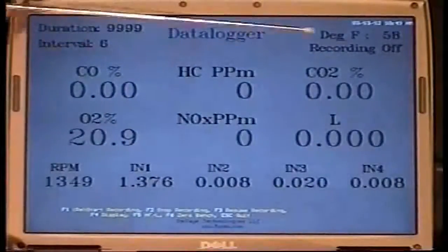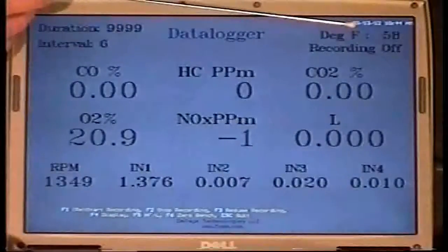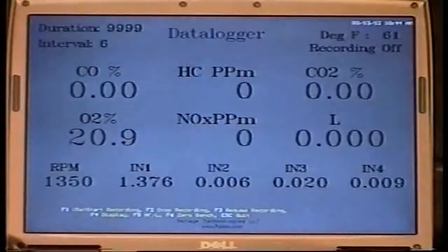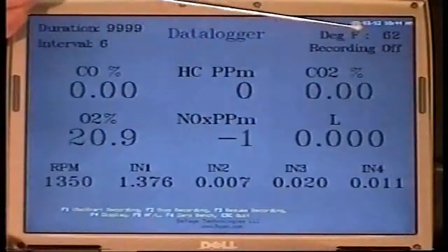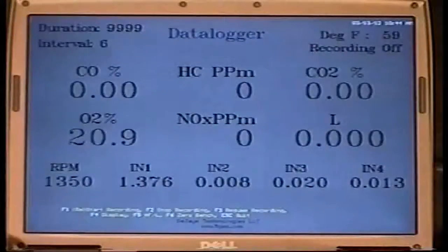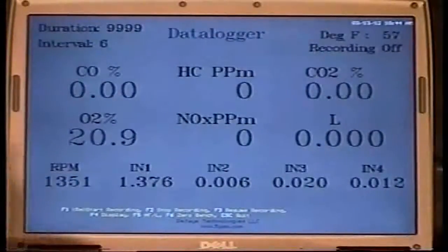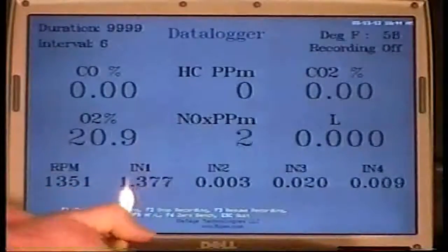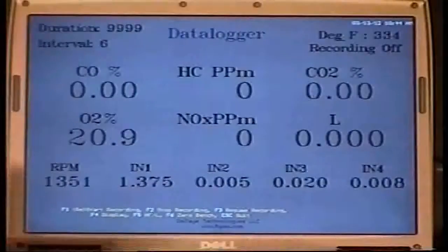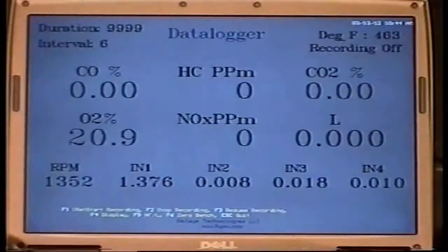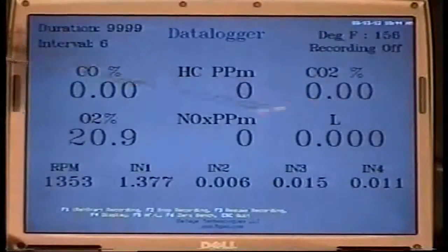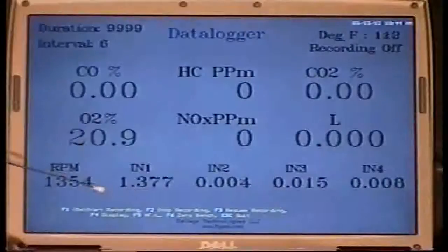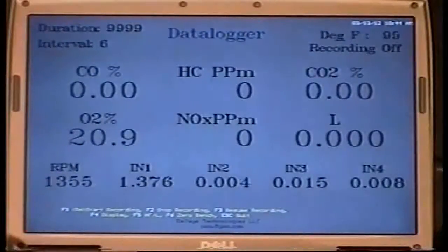We also have a temperature sensor up here. This is a K-type thermocouple. I'm using an Omega module, and this is for exhaust temperature. And I think it maxes out about 2,300 degrees. And as you can see, it works quite well and rather quickly. All of this data that's on here, your gases and all the data from the expansion port, becomes part of the original data file that is filed in the Excel format.